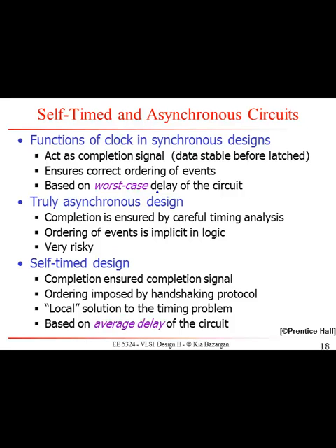If you look at clock design, take an adder for example. In an adder, you're going to look at the worst case scenario. You're going to say my carry propagation is going to go from bit number 1 all the way down to bit number 64, and that is the worst case scenario. It might happen just 1 in a billion, but because it might happen, it means that your clock period has to be long enough to accommodate for that, right? But on average, you're probably going to be running a 20-bit carry propagation, so it seems to be an overkill.